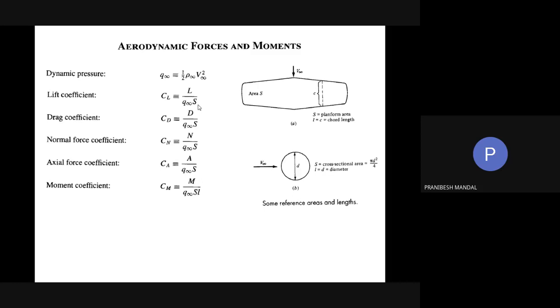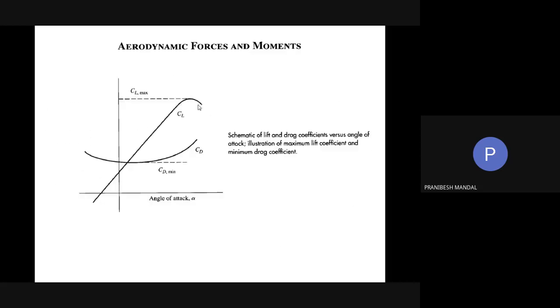I think by the time he should have moved up, there had been a bit of delay, and such a bit of delay can cause a huge problem. Because under the thunderstorm, under the turbulence, this particular curve, with angle of attack up to a certain limit, CL will increase.